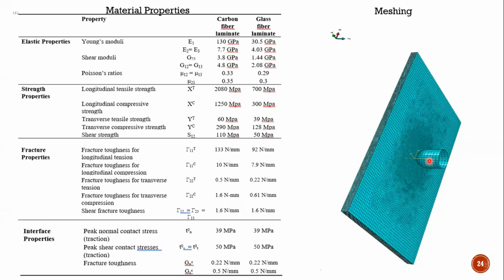After the meshing strategy, we come up with a particular characteristic element length, and then we define element sizes lower than that characteristic length.